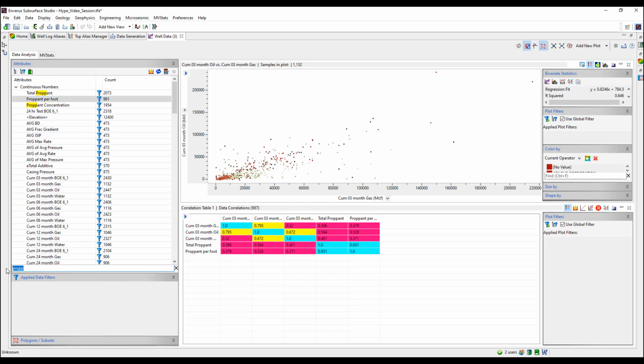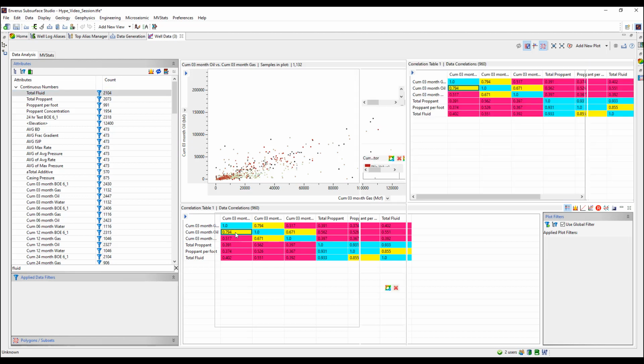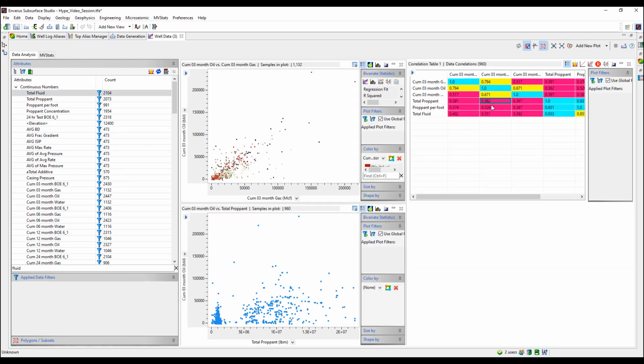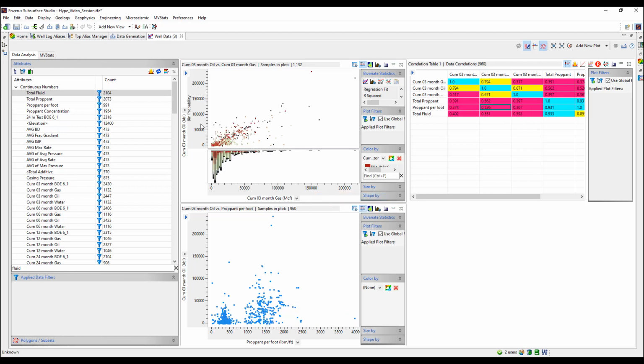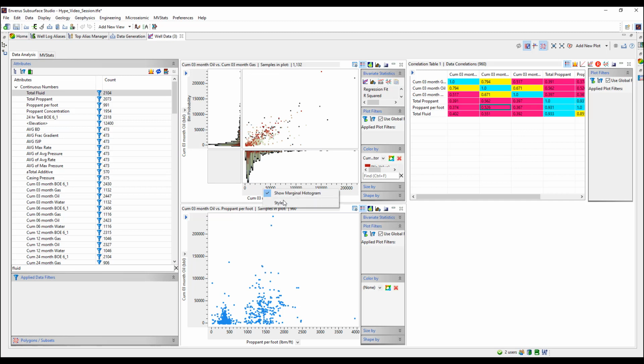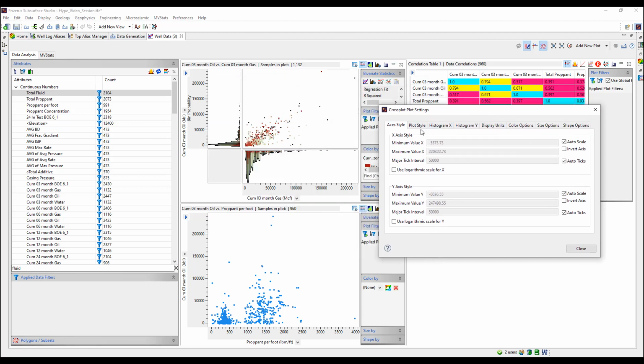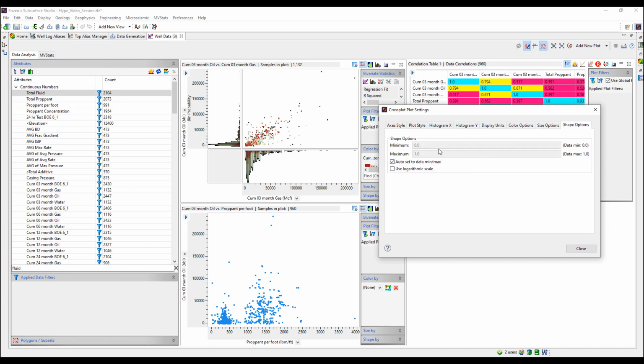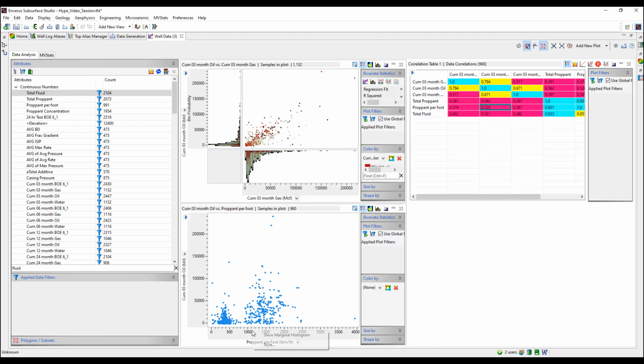We suggest using the new correlation table to facilitate data correlations in the XY space. Once here, users can populate a data matrix consisting of any number of attributes and then immediately get the linear correlation between them. Just double-click on any cell and the matrix will open a separate cross-plot for the corresponding attribute pair. And here I go with the right-click options again, so you can update the data and display in that plot.